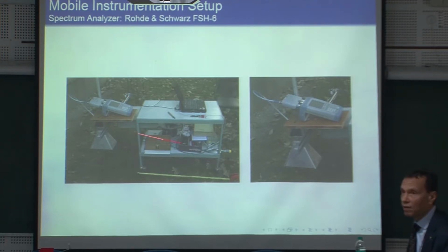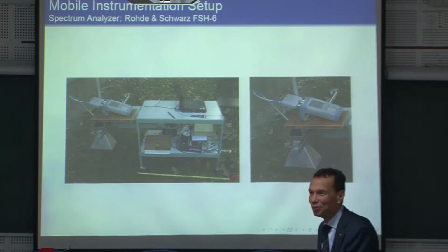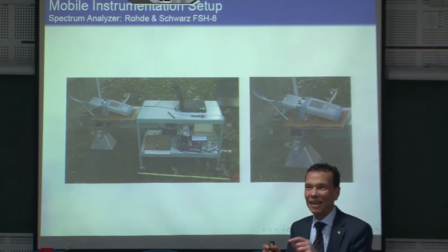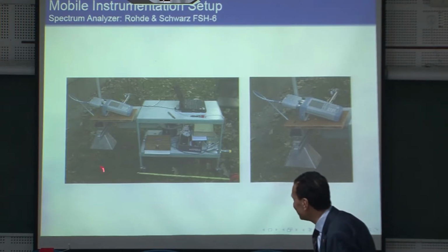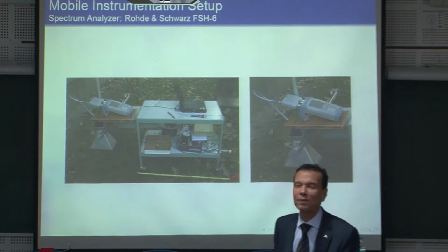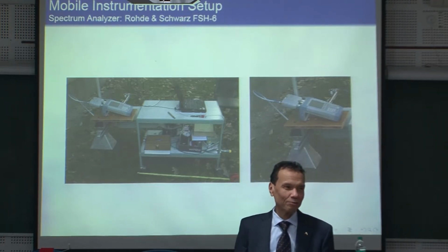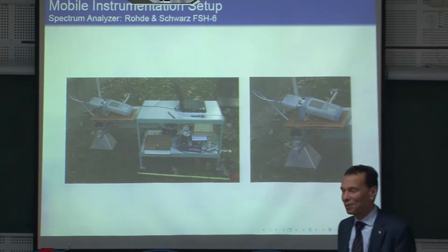This is a laptop for the signal processing. The whole thing here, and you see here below the network analyzer, you see the antenna here for field measurements, and you go with the carriage this way. This going with the carriage is not automatic now. It was just to draw lines on the ground, and you adjust the carriage exactly here and there, and you measure with this the center line of the antenna at this point and at this point. It is primitive, but it is also a prototype, a laboratory prototype. But you could get your image this way.